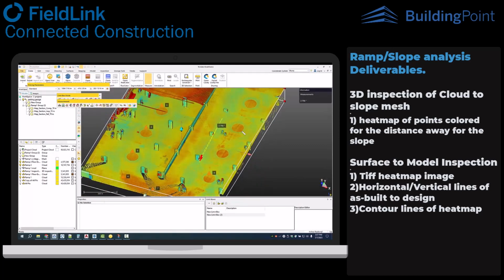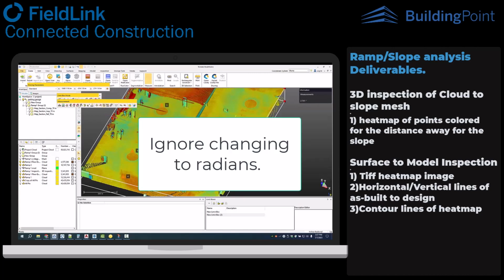In Realworks, I can come in here and actually just take a few sample lines to get an idea of that slope, which is about 2.7 degrees. So if you're going to do degrees and you want to get the kind of the rise over that run of that entire length, remember if you do the arctangent, you're going to actually want to convert it to radians. You can get that answer here, and instead of using degrees, actually convert to radians initially.